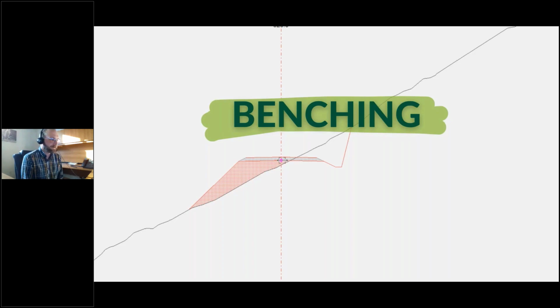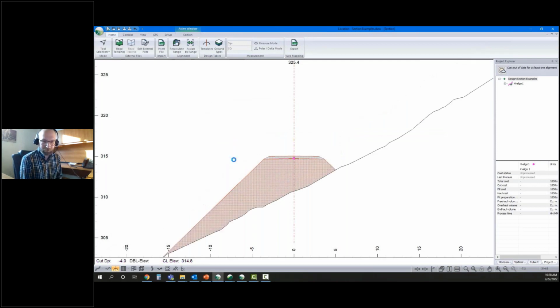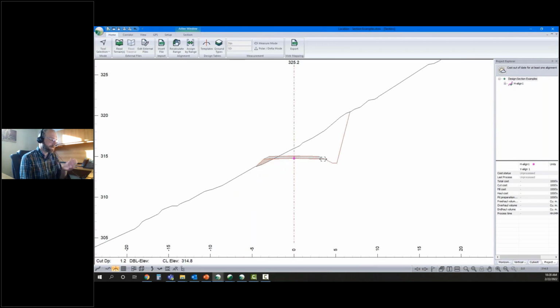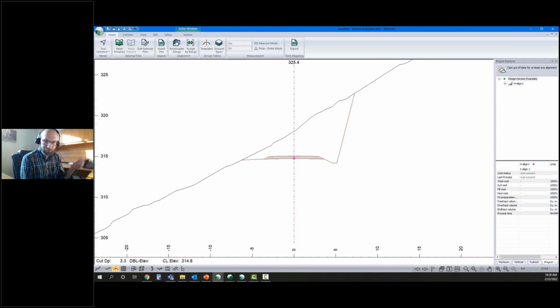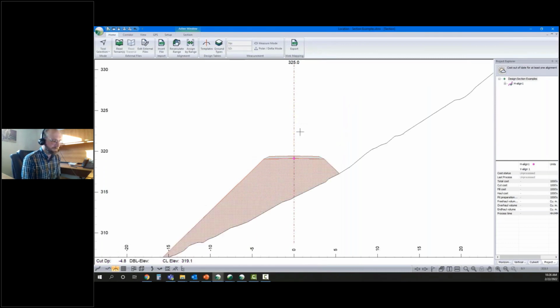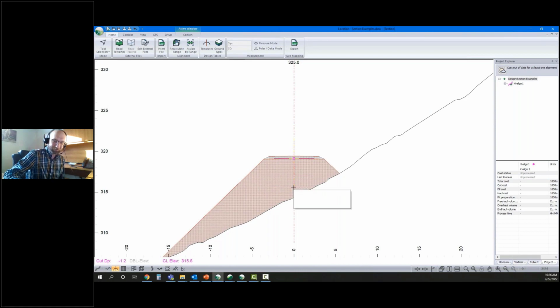So we'll just look at a quick video here. It's just a function of whether you move in or you move out or you move up or you move down. So if I take that alignment and move it out while we're in fill only, if I pull that in, we're 1/4 bench, half bench, 3/4 bench, and then we'll go to full bench with daylighting, and it may be that you get prescribed full bench without daylighting. So you leave a wedge of material there. And same for moving it up and down. And we won't show the whole thing here. It's pretty straightforward.